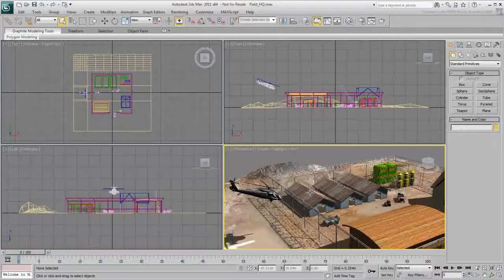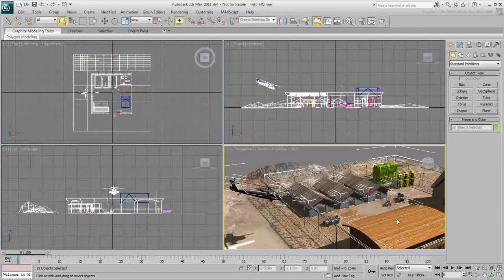When the objects you want to select are close together, it's easier to use a region selection. By default, this region is defined by a rectangular area and is achieved with a click and drag. All objects contained within or crossed over by the rectangular region become selected. We refer to this mode as crossing mode.